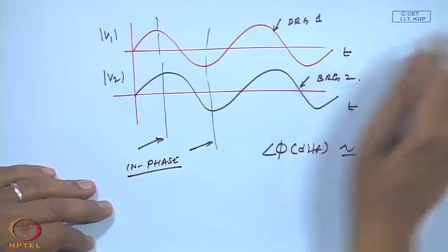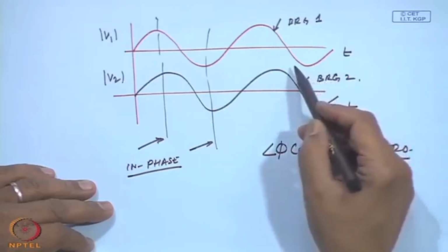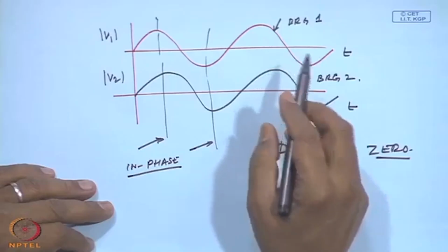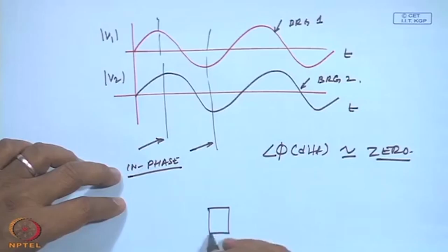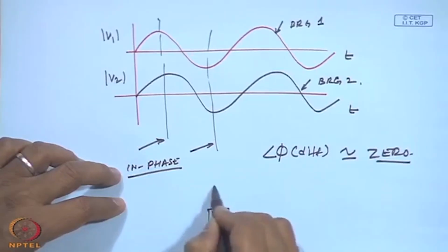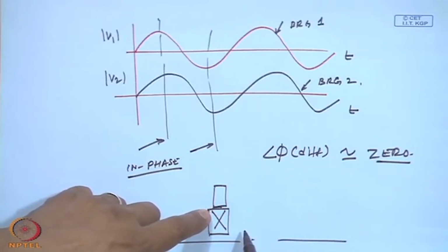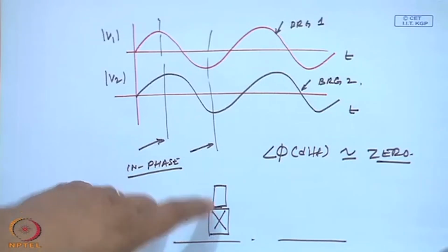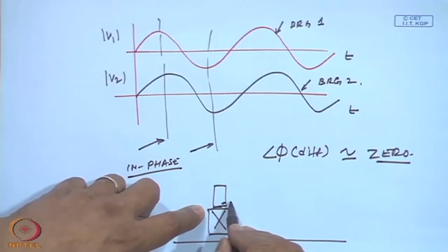perfect. When I drew a sinusoidal, if I show you an unbalanced time history of a signal, this is no way close to this, because in a machine everything is mixed up. This sensor which you put on the bearing, okay, this measures a lot of things. This measures the bearing vibrations on top of the unbalances. Suppose the shaft had some other problem, like things were loose, the shaft had a crack, or shafts were misaligned. So, all these vibration signals are going to come into this accelerometer here.